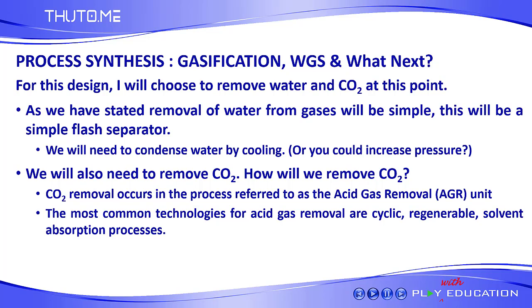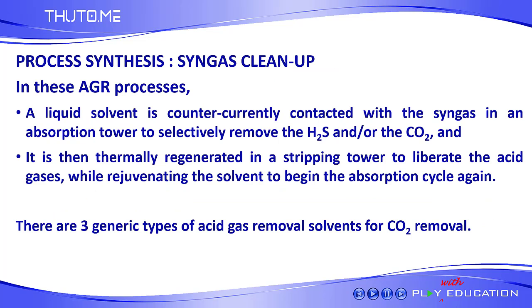Removal of water: cooling and a flash separator. That's easy. But now you are left with gases that have CO2. You have CO2, hydrogen. Now you need to remove CO2. In the AGR processes, you have a liquid solvent that is countercurrently contacted with syngas in an absorption tower to selectively remove hydrogen sulfide and/or CO2. Usually the acid gases in the synthesis gas, in most cases, do include hydrogen sulfide.